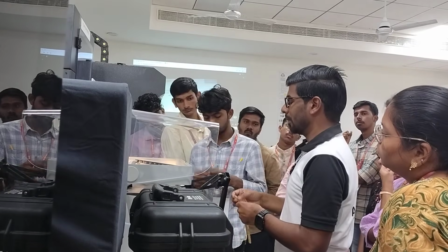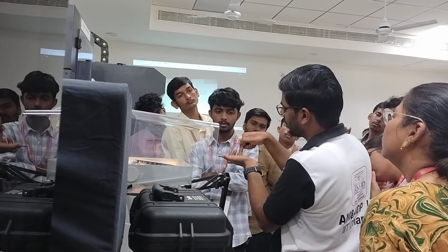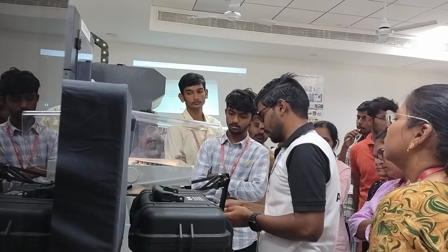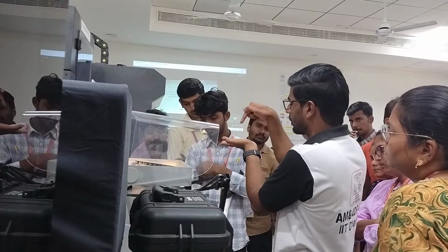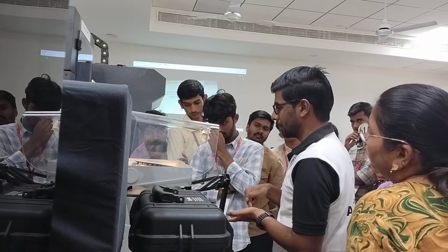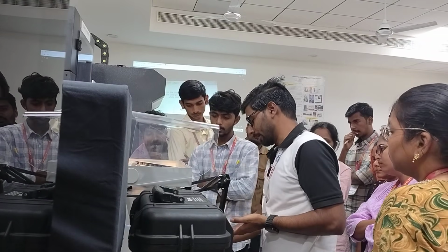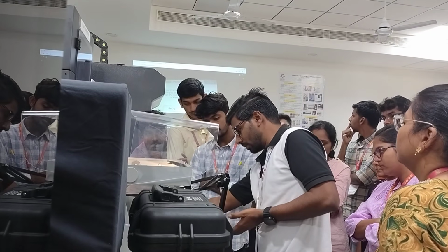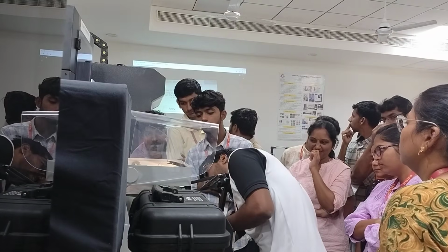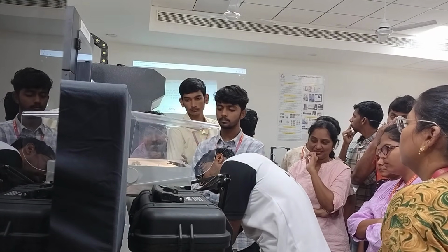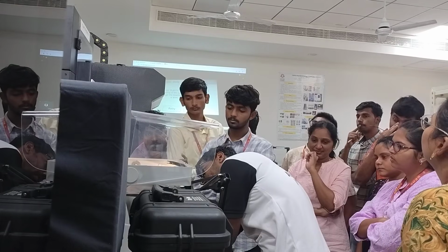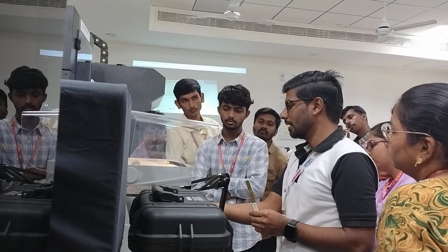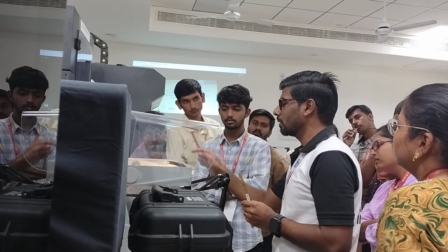This is required because when the deposition is happening, it must not deposit in the air, and the nozzle must not go and strike the bed. So now we know that there is a proper clearance between the bed as well as the nozzles, and the bed is also aligned. I'll click on next. It's moving back to the right position. Oh, this one is again telling me to do the same thing. Can anybody tell me why it is telling me to do it again? Might be the gap is less. Yeah, since I have adjusted here, there might be a chance that while adjusting, this might have gone down or something might have happened.